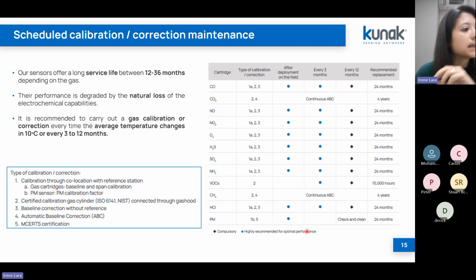Okay, and in the case of the particles, it's a little bit different. So we have the certification, so we don't have to do anything, or we have the option of using a reference station if we want to use it. And then, yeah, we recommend to check it after deployment on field, and then every 12 months to check if the sensor is working well, and if not, maybe it could be needed to clean the sensor.